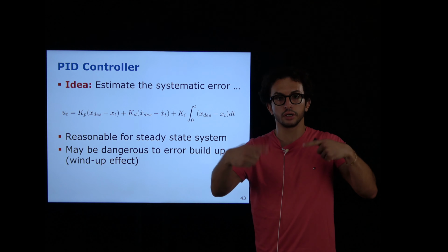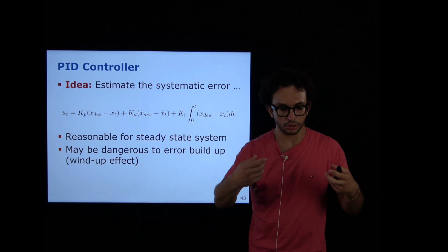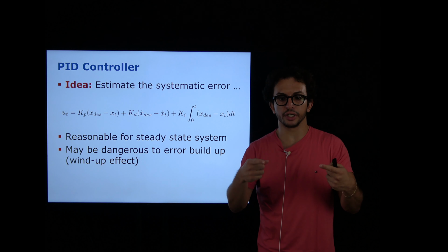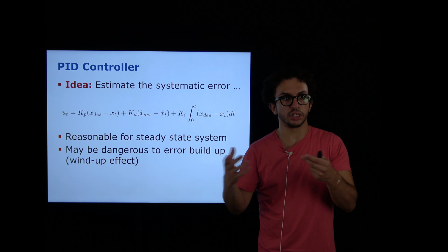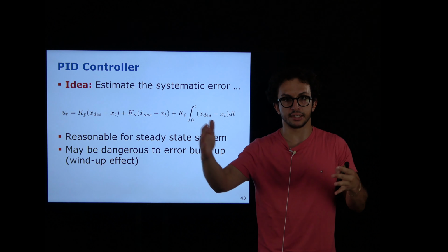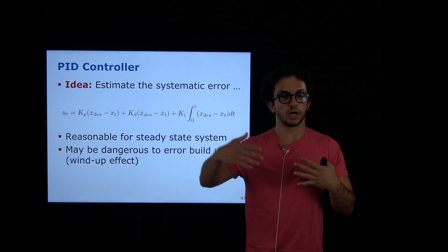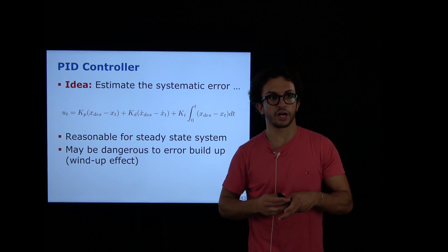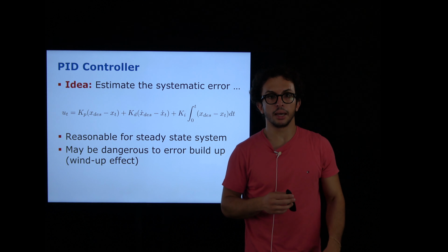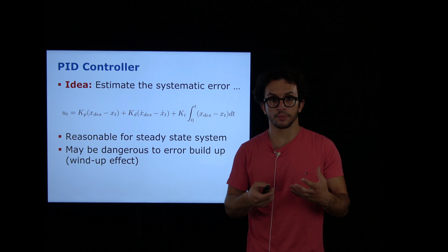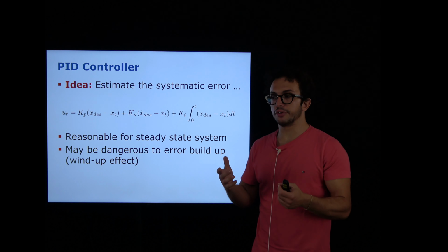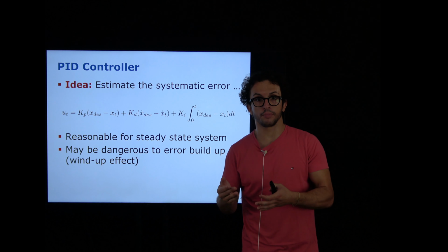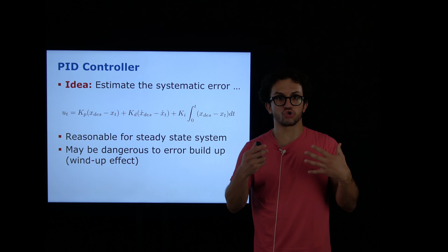So the wheels are moving, because you have a sensor reading that tells you where you are. The wheels are moving, the state is not changing, and so the error starts going like crazy, because the error goes up and up. The desired state is probably somewhere else, because the robot should have kept moving, but is not able to move because it's stuck. So there's a huge difference between where you want to be and where you actually are.